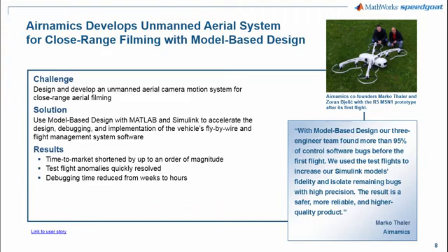In preparation for flight tests, they generated code from the controller model, which they compiled and deployed onto an onboard real-time target computer running Simulink Real-Time. In some cases, the team was able to accelerate development iterations by updating the model and generating new code in the field between the flights.